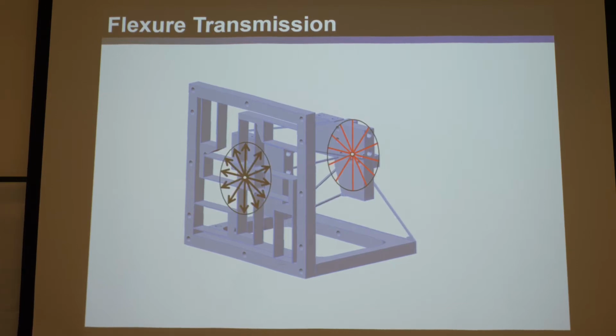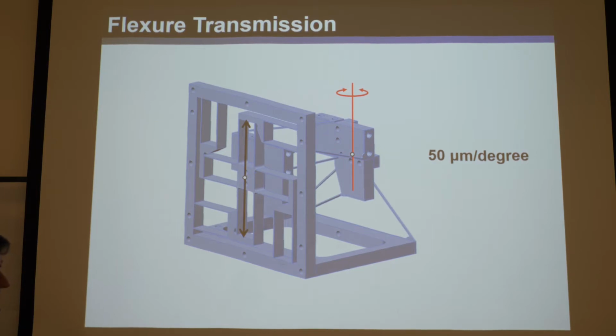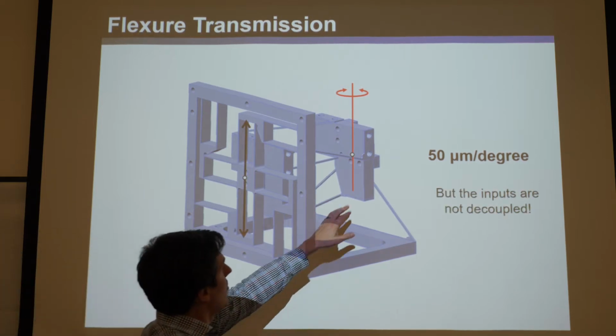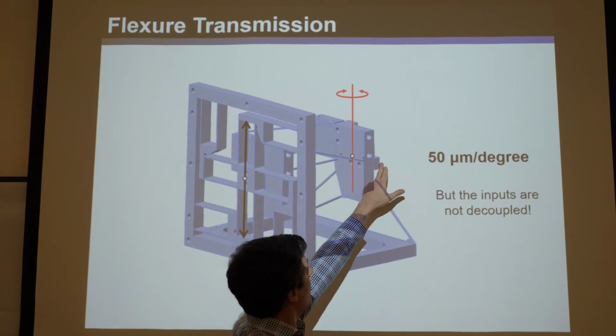And so now you've got this constraint so that if you rotate this back stage about anything that's guided to only rotate in the disk, you're going to get an output transmission of the output stage with the transmission ratio you wanted. But we have a problem, because if, say, we rotate this, right, sure, we'll get the translation here that we wanted with the transmission ratio, but this guy will move over.